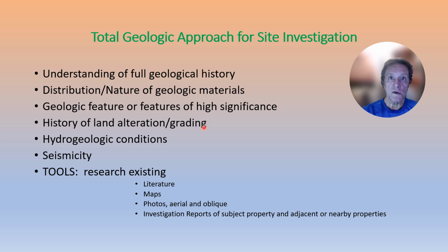History of land alteration. Was there any previous grading done on this piece of land? Were there cuts made? Were there fills made? These are critically important in assessing a property.